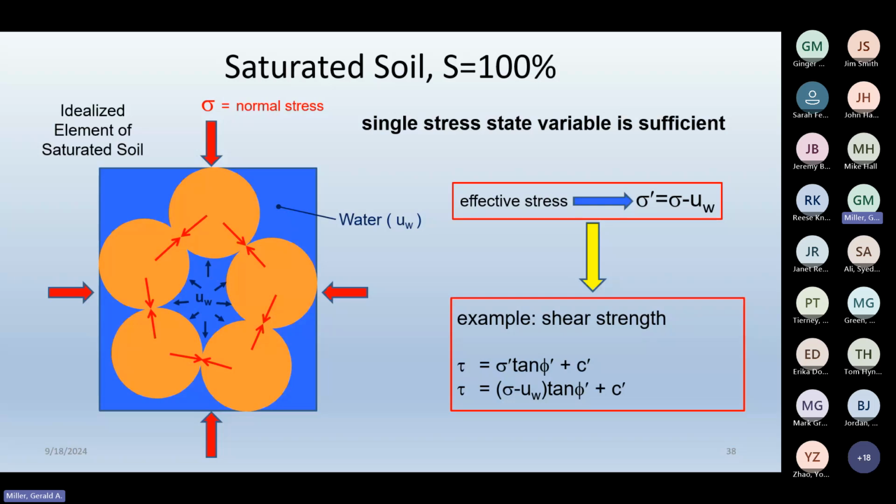So it makes sense that that effective stress, which describes essentially these contact stresses averaged over some engineering area, that's what effective stress is, right? It's a measurement of contact stress averaged over a larger area, that engineering area.